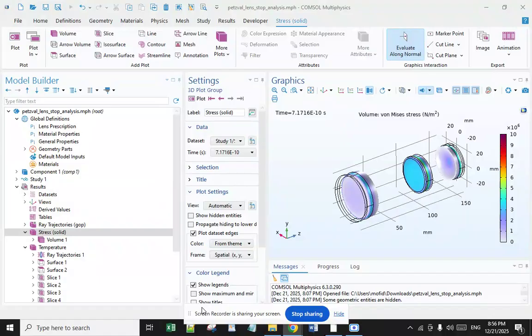And what is the process? Since the material may expand 4 to 5 times under a vacuum, the mixing container must be large enough to hold a volume of 4 to 5 times the amount of the original material that is being vacuumed, to allow for the expansion.